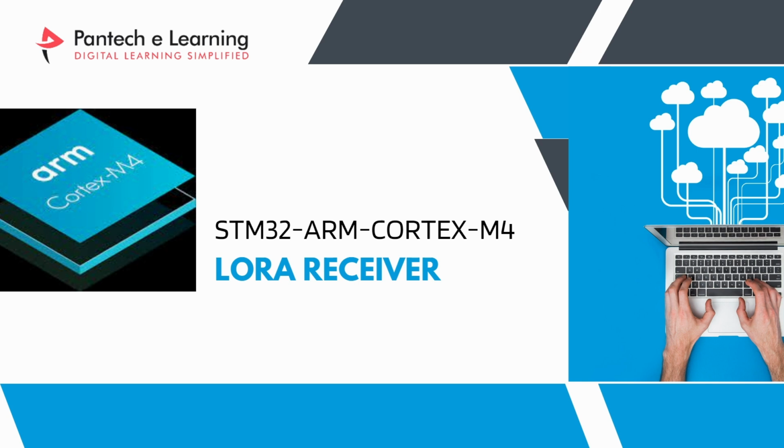So what it is going to do is send all the data, soil moisture data and temperature data, the pump state, the time the pump is running, all these data to the ESP32. What the ESP32 is going to do is connect with the AWS cloud and update the data in the cloud, and by that we can see this data on a PC or a smartphone, and we can also operate the pumps.